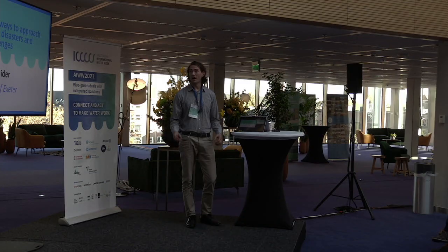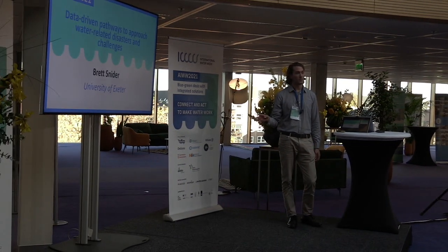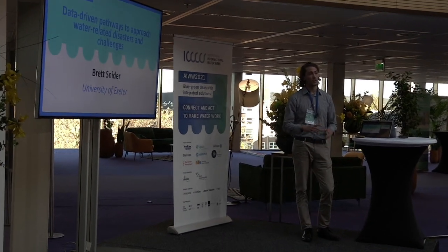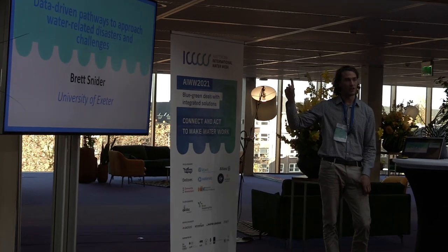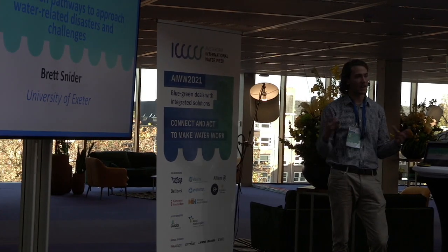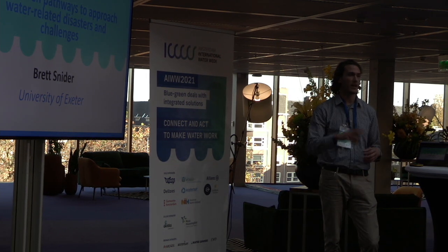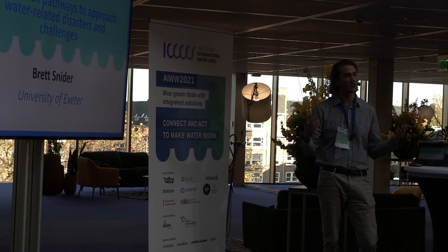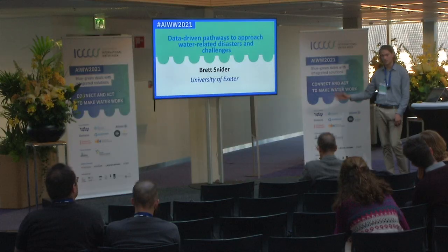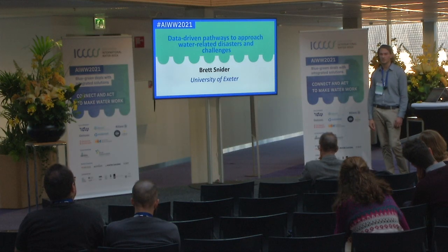Yeah. So right now, just working on the pipe burst anomaly. But if you look at the anomaly detection, the model that I've developed is using an exponential weighted moving average. So that just helps be quicker. So it's not an actual machine learning model. It's a little bit quicker in that regard, and doesn't need as much training.